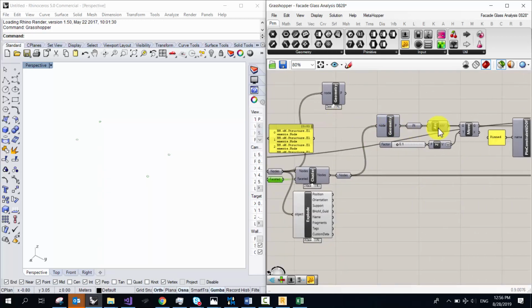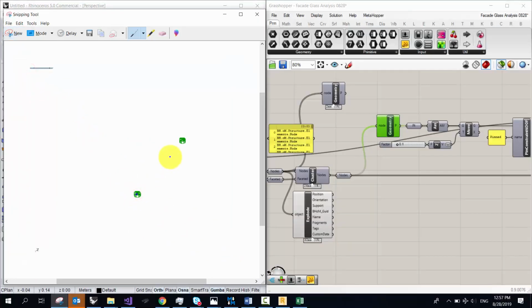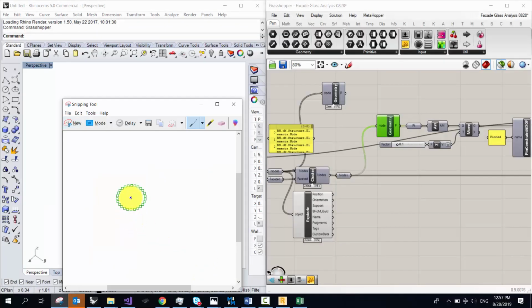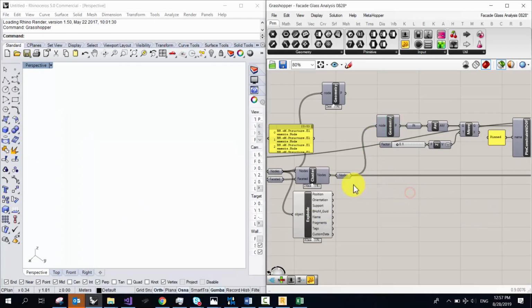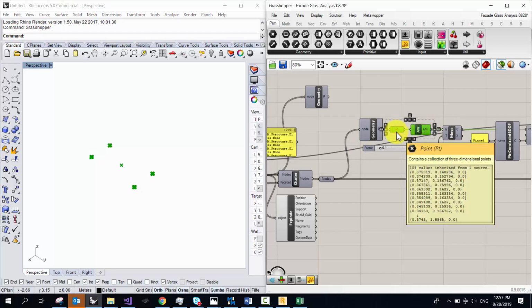Okay. So does everybody get what's going on here? What we expect to see at this point, we saw it on Monday, was instead of seeing one point out here in space, that's the average. Yes, that's the average of all the points. We want a point here and a point here, not a point here. Yep. So what we really wanted, based on that original sketch that I showed, was we want the master node. We want a node right here that will be the master node, and then we'll draw a bunch of rigid links off of him, be the slave node. Right? But Sung originally, right now, he's just said, here's 104 points. Please average them. So is there anybody against what's happened here? From a logic standpoint, logically, you're getting the right answer.